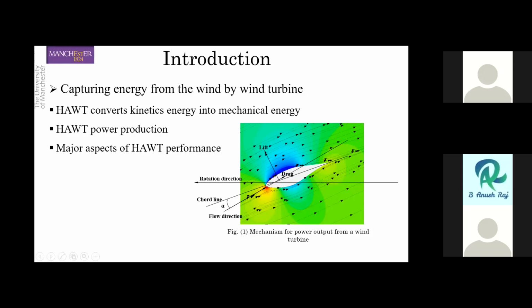The top of the blade experiences faster airflow, and as a result, less pressure. As the pressure on the top of the blade is less than that on the bottom, a resultant force acts towards the lower pressure, producing the lifting force, which I mentioned before. This force is always normal to the relative velocity here, and is tilted by an angle called the angle of attack.